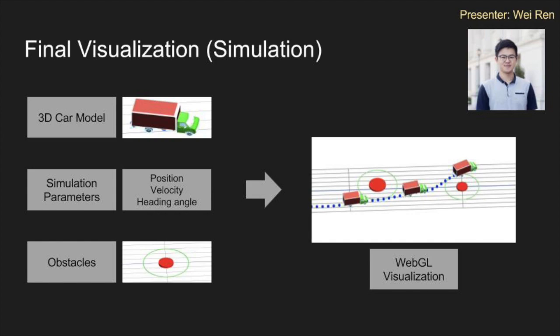The application used data from state variables, input variables, and output variables of the MPC system to drive the WebGL animation loop to visualize the real-time positions, velocities, steering angle, heading angles, and so on. The application also set the parameters of the WebGL camera to follow the car in real time.